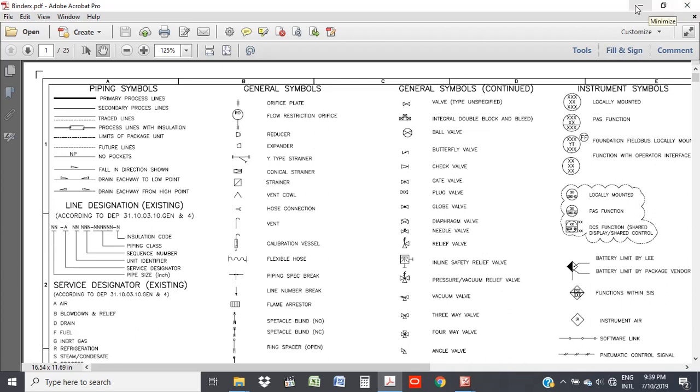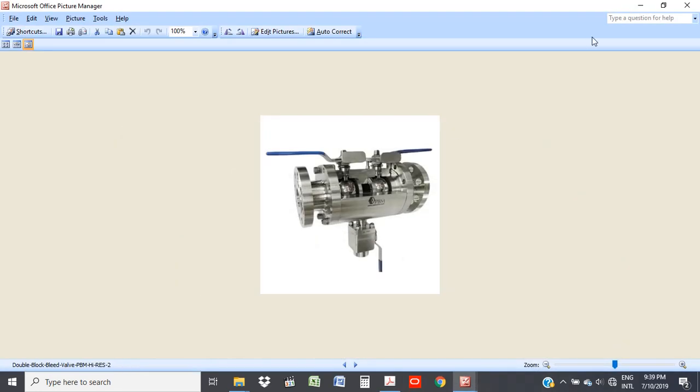And if it's not necessary, then don't waste the money doing what we call an overkill design, or over-designing the plants, like putting globe valves everywhere when you can just use a normal ball valve, which wouldn't be that expensive.